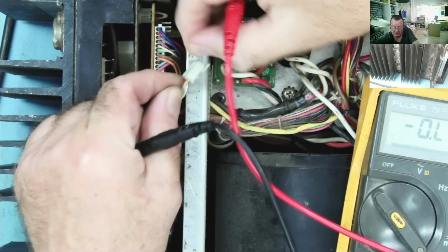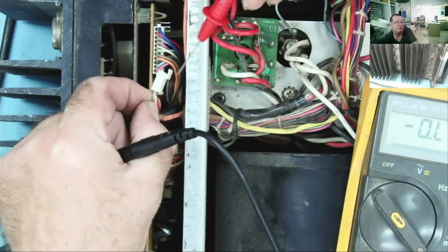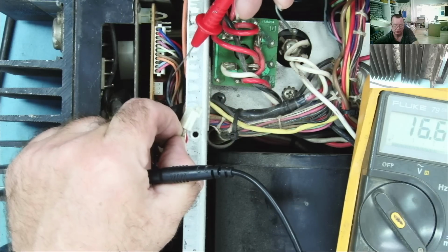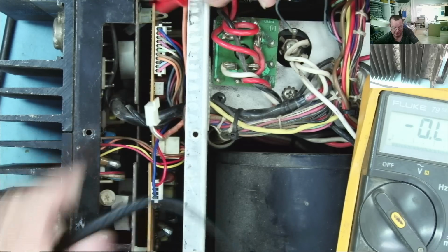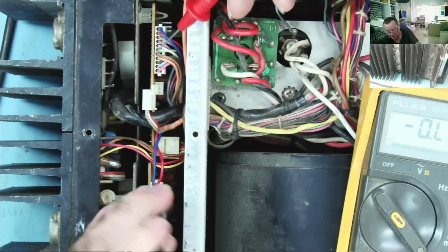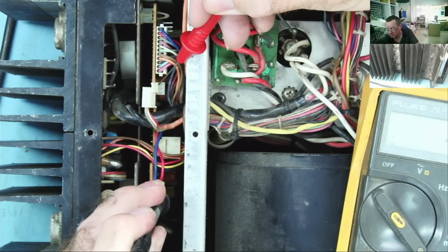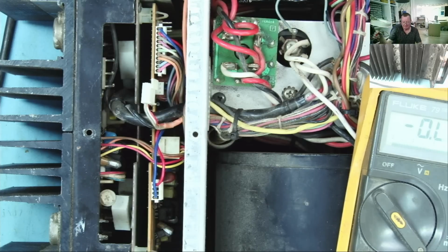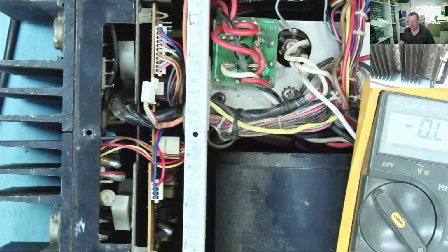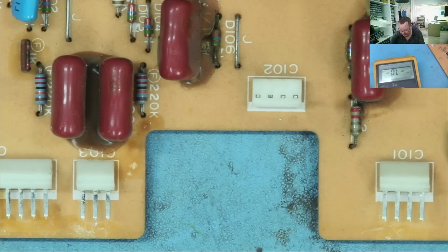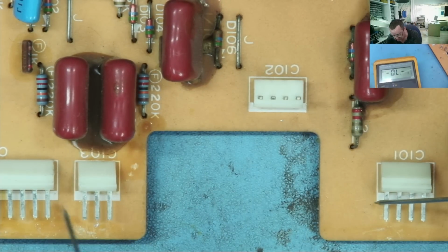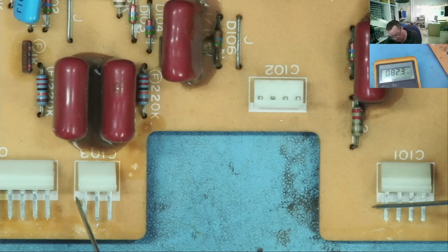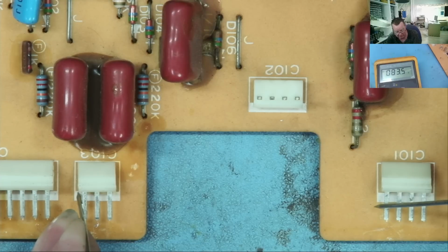You can see like the screened wire. So effectively this is just connecting that point to ground, which is why when I disconnect this, the resistance goes away, but the low resistance is still on this board, 80 ohms from here to here. That's just the path from there to ground. Okay, back on this one again. Here's the board. I've taken it off the amplifier. Here is the 80 volts plus, and this is the ground connection on here, and there is the 83 ohms I'm actually reading now.